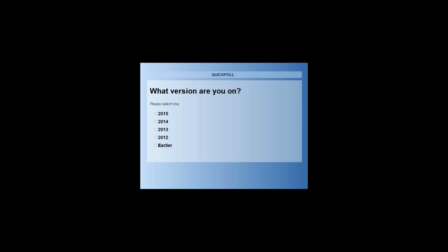And while everybody's filling out the poll, I will say that, yes, 2015 is the latest version. For those of you who are using 2015, please, for all the love of the world, please keep up with your service packs. I believe there's a third service pack that just got released. 2015 did have some issues with the release, mostly because they changed the graphics engine, and Autodesk is working furiously on patching some of the issues. So please keep up with your service packs. Also, please keep up with your video graphics drivers. Get the latest video graphics driver, and a lot of the problems that people are experiencing will go away.